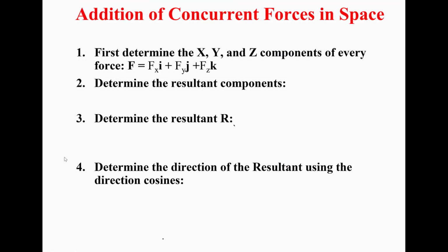Now let's move to the two applications we're going to cover for today. First, we're going to see how we can add forces in space at a certain point. The first step is to determine the x, y, and z components for every force. Then the next step is what? To determine the resultant components.